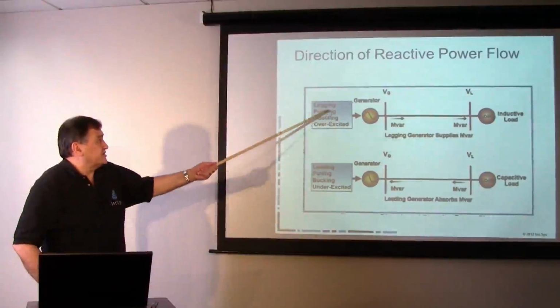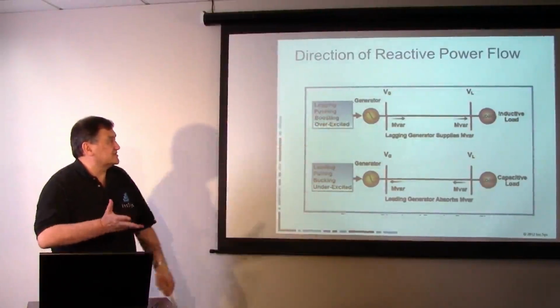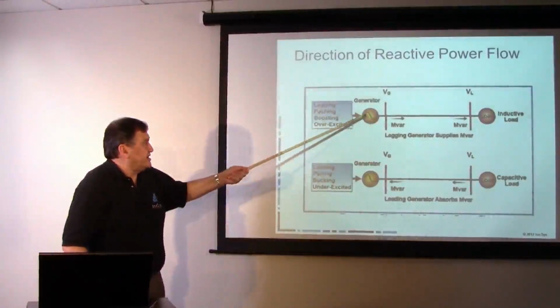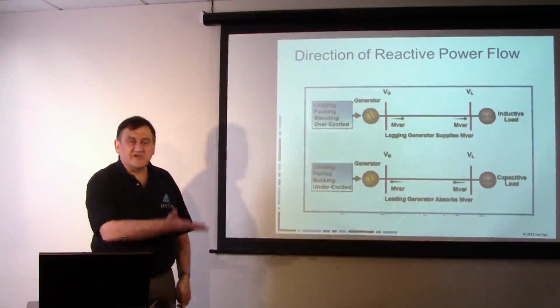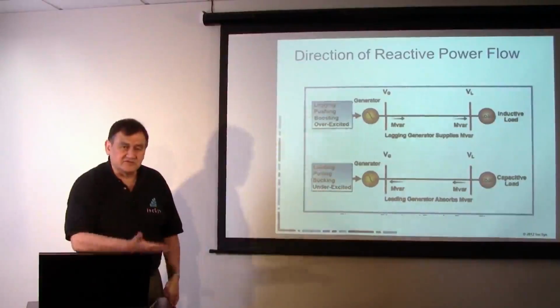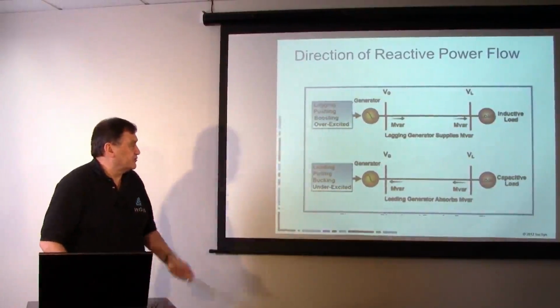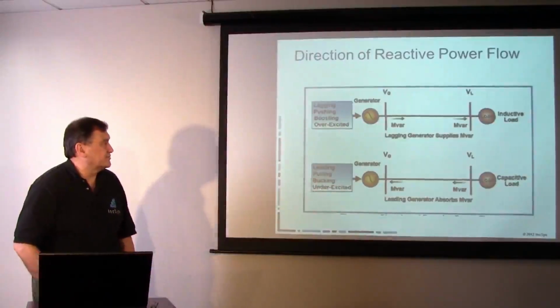So we can say that generator is pushing megavars onto the system. We call it boosting because in this mode it is actually helping raise the voltages. So the idea is when we're raising voltage, we call that boosting. When we're lowering voltages, we call that bucking.